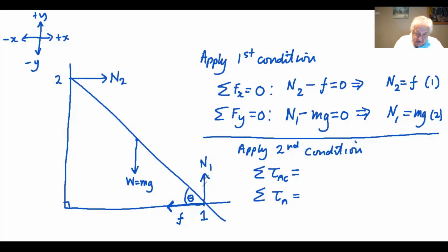Now, here you've got a number of forces acting, and it depends on what things you're given, but you try and choose the axis of rotation through the most unknown forces. Since I'm not given any forces here, I'm going to pick this as my axis of rotation because it contains so many quantities. It has F, it has theta, it has N1. And by choosing it like this, it will simplify the calculation.